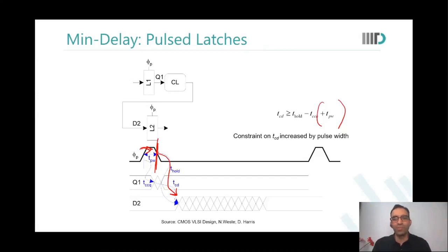Yes, sir. So what's the big deal? I'm getting a flop kind of functionality at half the area. But sending these pulses over a distance would be a challenge. That is the challenge. I agree. I'm not saying it is easy, but there's a clear benefit there. Because the area is lesser, the RC delay, due to which I cannot send short pulses to long distances, also reduces.